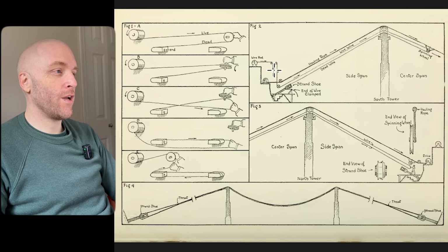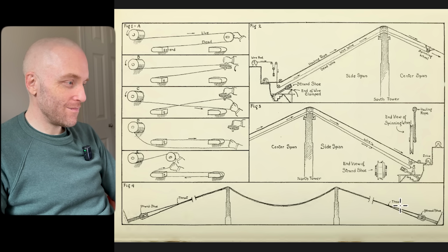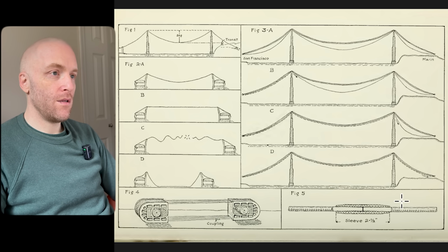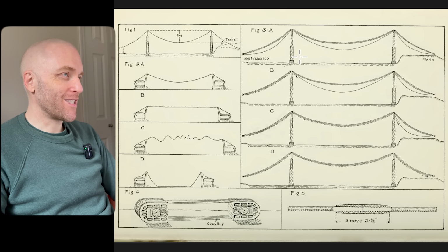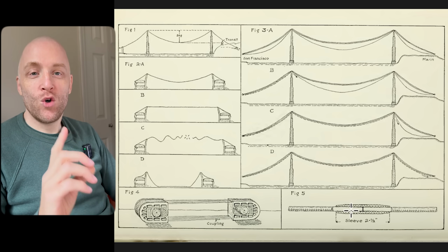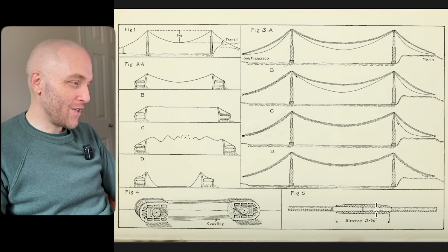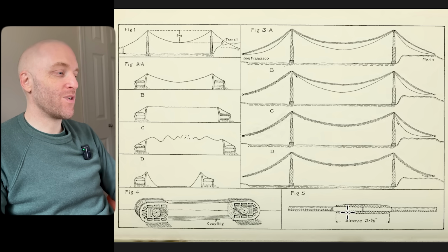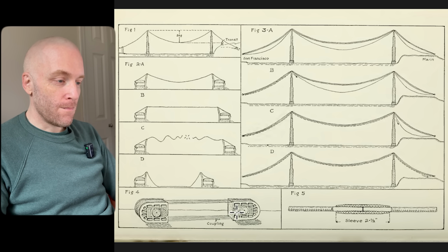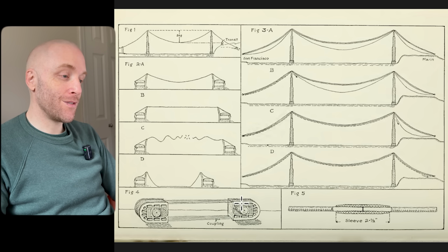But you can see the counterweight and the hauling rope and then the dead wire, the live wire, and everything is here. The throat, which is the name of that little bracket, the sleeve before the loop goes around the shoe. And he's just explaining some of the reason why they do it this way, the strand adjustment. This is called cold swaging. That's what this is called, when they join things together with the ridges and the special sleeve that's pressed over the wire. And you can see the little coupling down here. So this model of the shoes and the loops is actually really good.